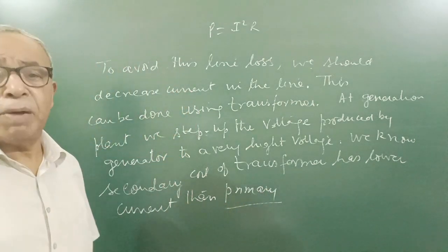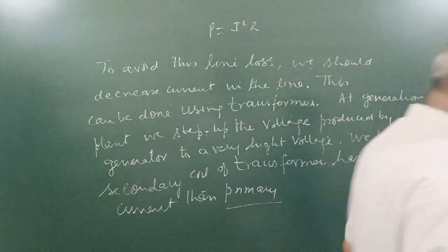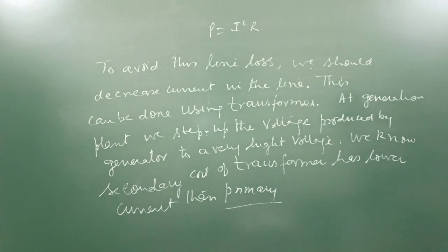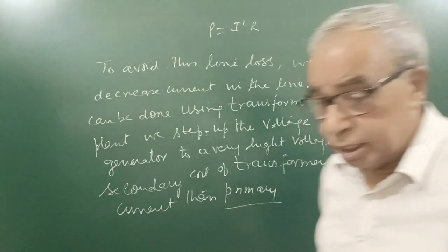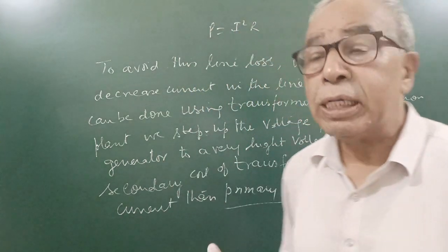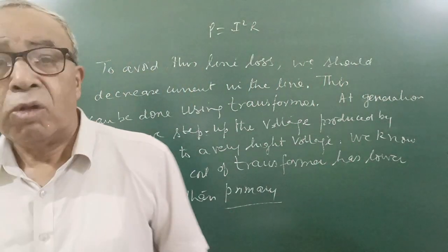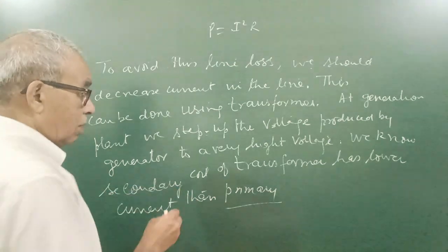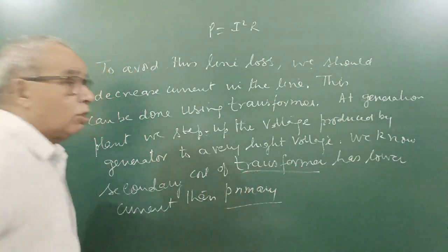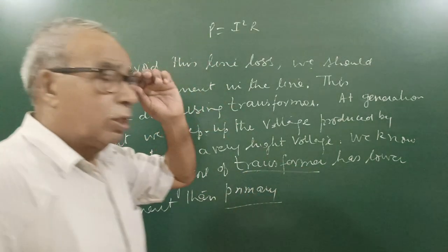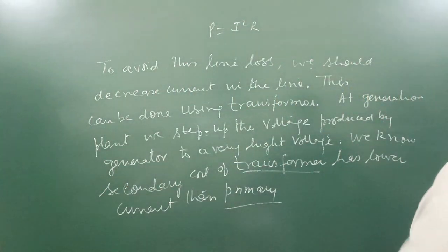So the power produced is transmitted through wire at low current and high voltage. Now in towns, actually we are using 220 volt, and this step-up transformer may be of 40,000 volt, 20,000 volt, depending on distance.